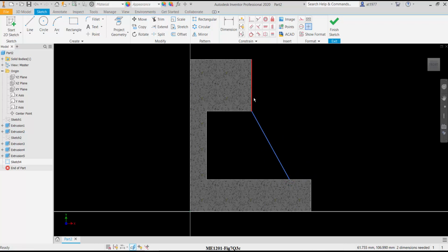Notice this green line is there. So what you do is that you need to turn it into a construction line. If not, you affect the rib command. The distance from the point to the extreme right edge is 24. If it's not long enough, just extend this to here. But do take note that because this line is not being projected, it doesn't touch here. So what I need to do is I just project this edge as well. Make it extend to the bottom.